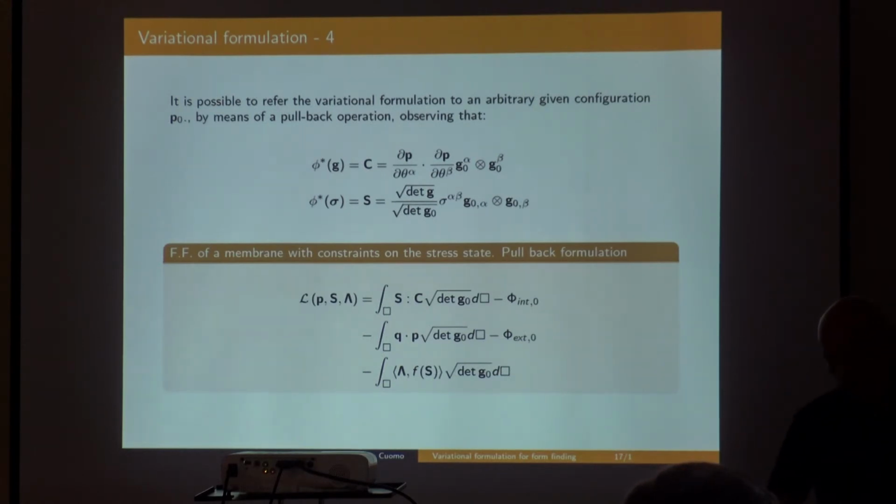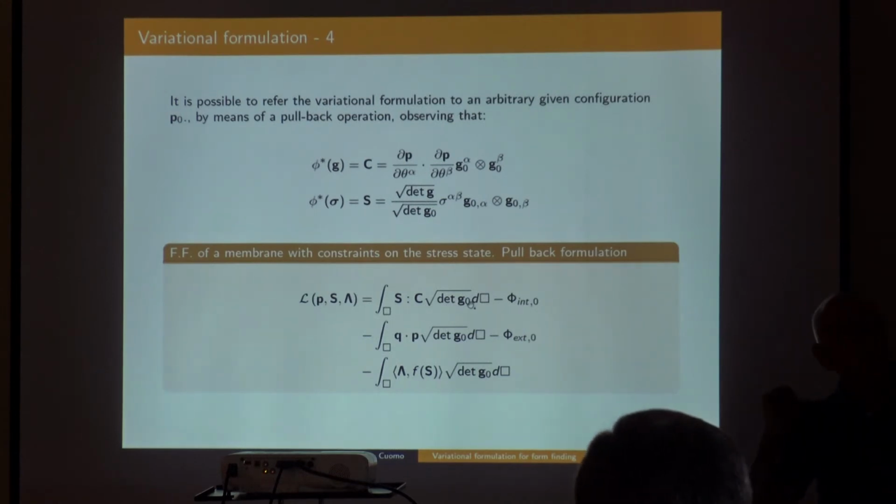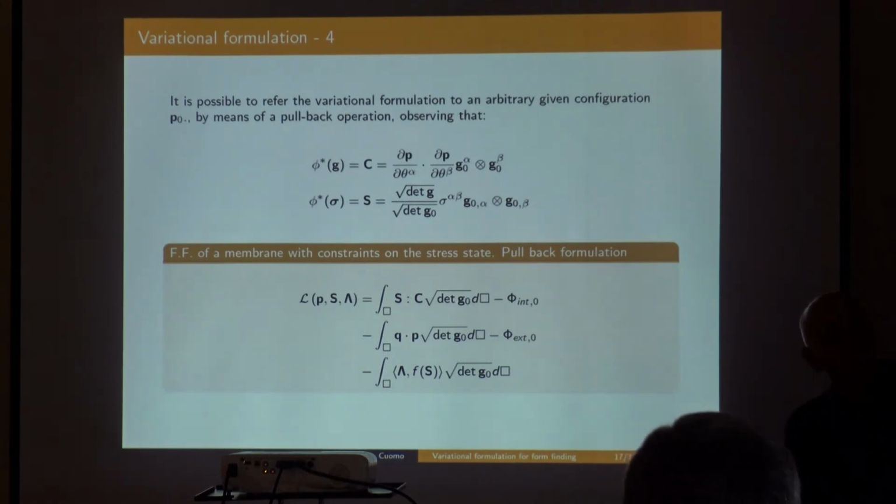Okay, I started this. You can do the same. So this is even a three-field functional. The variation gives you some nonlinear equations for finding these three fields. I will show later how then we proceed in order to compute these three fields. Now, one advantage of doing this pullback is that now there appears the determinant of the arbitrary metric, which is known. So it's something you don't have to make variation on. It may be useful, simpler, but is not essential.